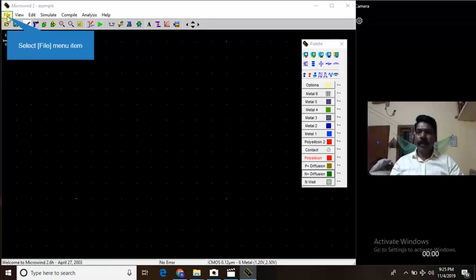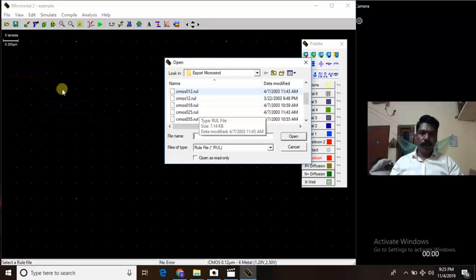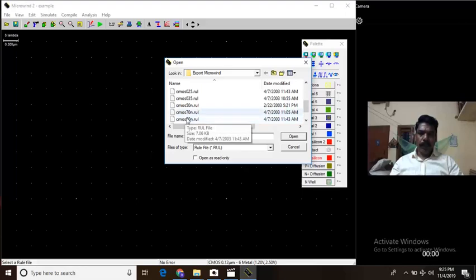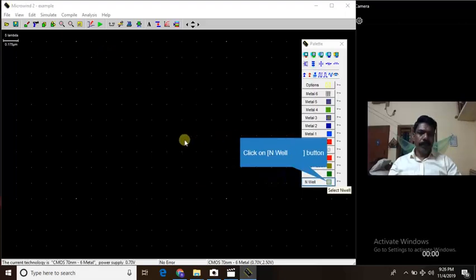First, what you do is you select a foundry. Go to File, and then select foundry. So it will open a list of foundry, that means .rule files, so design rule files. Select one of them, for example, a 70 nanometer technology, and open it. So it will open the design rules of that particular technology and the masking sequence in the palette here.